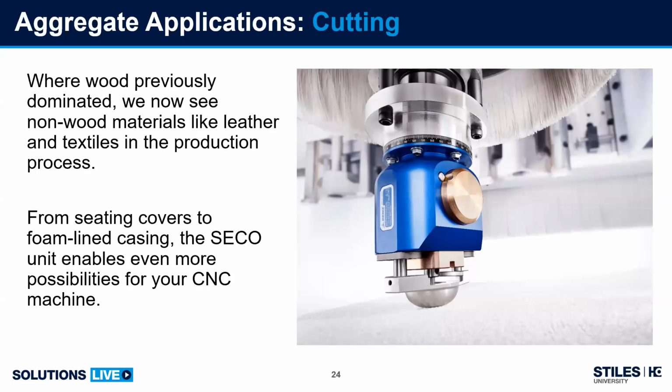Into cutting applications. So this is our SECO unit. This is one I would say we probably get more questions on than any other aggregate at our trade shows. It's unique looking, and it's very diverse in its capabilities. So what you see here, it looks like it's cutting some carpet, and you can see it's a little bit smaller, but right underneath that bell, you can see the knife unit itself. So this is a reciprocating knife aggregate, and the bell portion is actually a floating tracing shoe. It's got about 8 millimeters of float there.